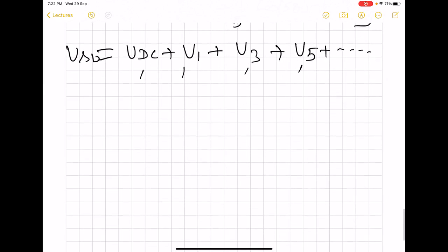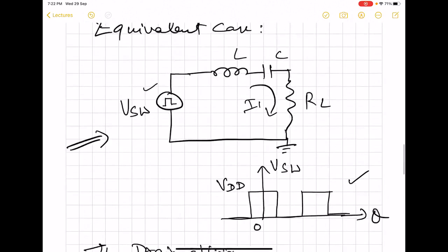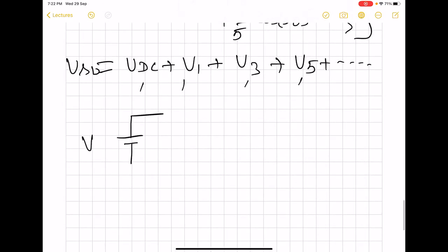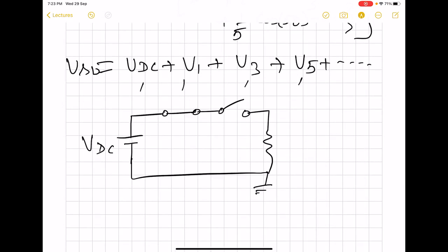When the DC is activated, in the equivalent circuit for the DC, the inductor is going to be a short circuit, but the capacitor is going to act like an open circuit, and the resistor will be there. So there is going to be no DC current; IDC is going to be 0 through the load.